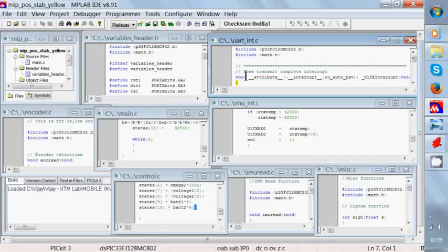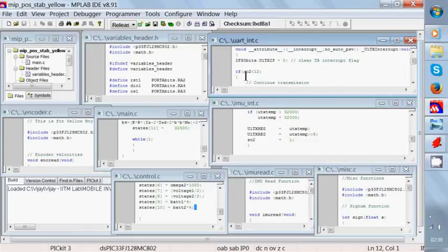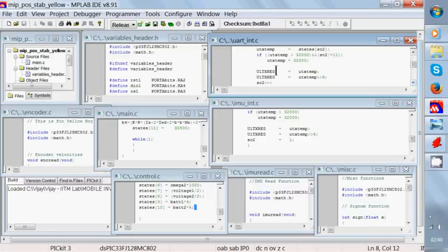And now this becomes an automatic process, even though some other program may be running, for example either an IMU read or control for the next instance. Once a UART transmit interrupt occurs, until the total number of states are transmitted, the flag is cleared and all other states are transmitted continuously. So after the next state is loaded into the transmit register, it goes back to whatever the code that was currently under execution or goes into a wait state.